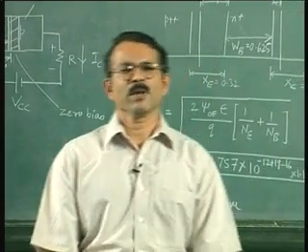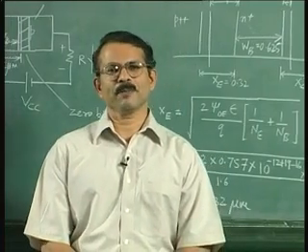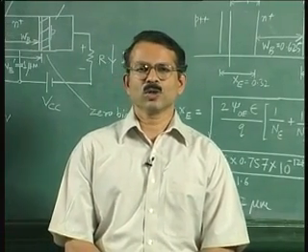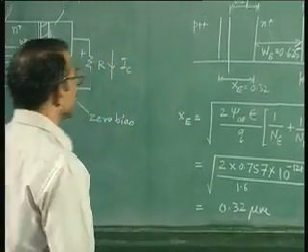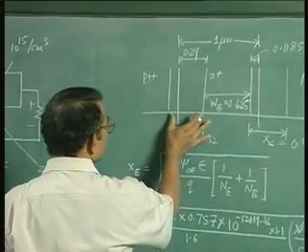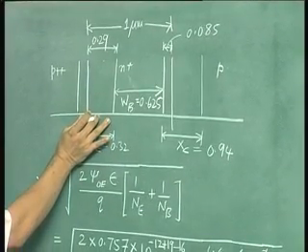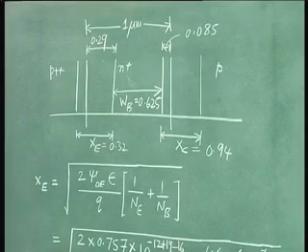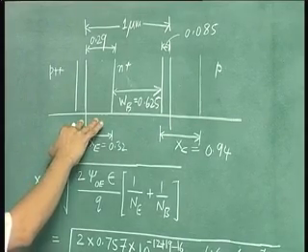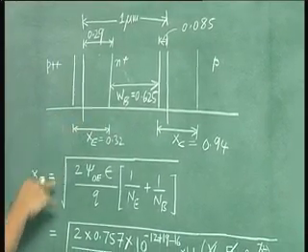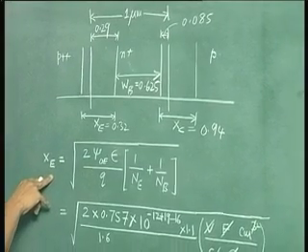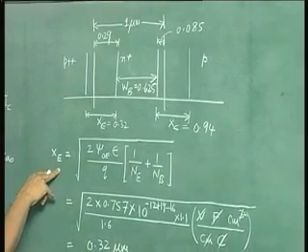As we said, our device will operate with a forward bias across the emitter base junction. So because of that, this depletion width which we have estimated at zero bias will get reduced. Assuming that the forward bias across emitter base junction is 0.65 volts, the new depletion width can be estimated as follows.